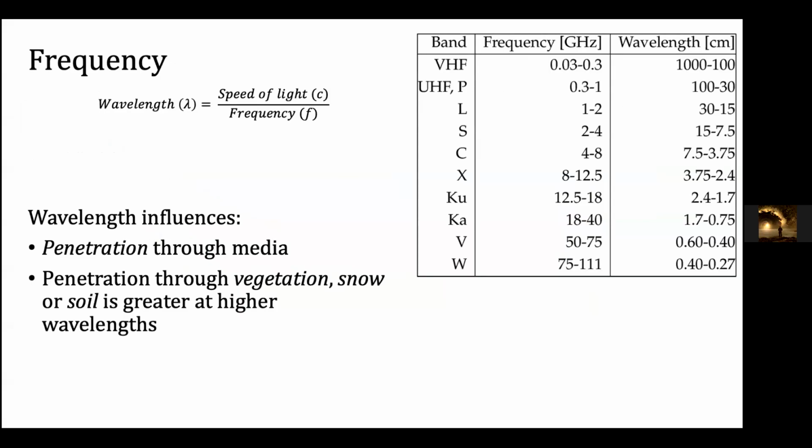So frequency will range from ultra high frequency, which is roughly around 800 megahertz. So P band will lie in that frequency range all the way up to K band. Generally, we don't have any radars right now which acquire higher frequencies than K band, because atmospheric parameters would affect the path of those frequencies, and so they are not particularly used in spaceborne and airborne cases.